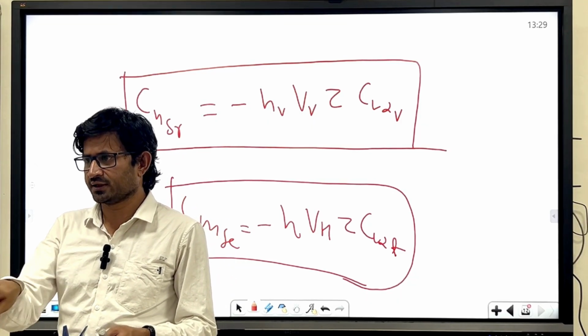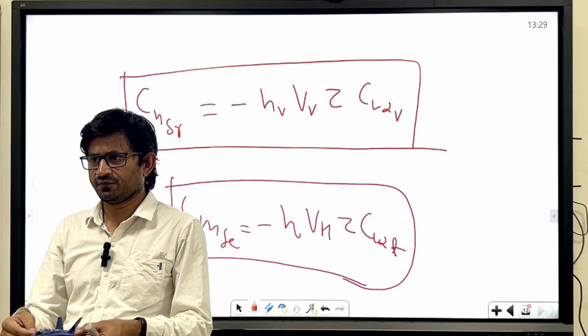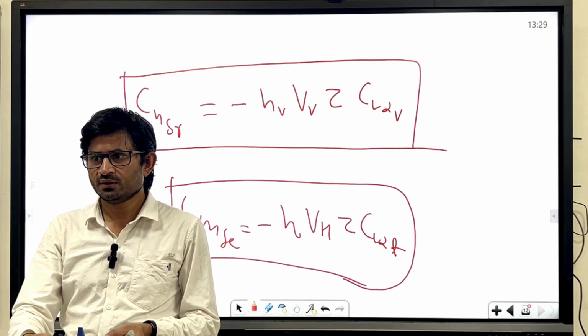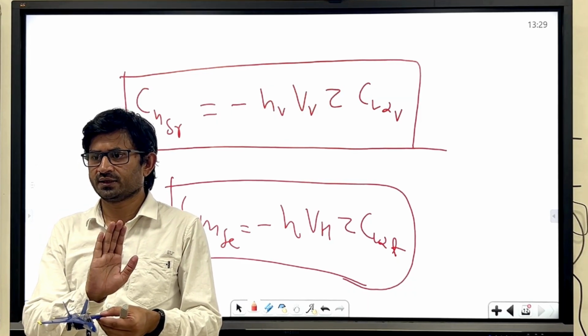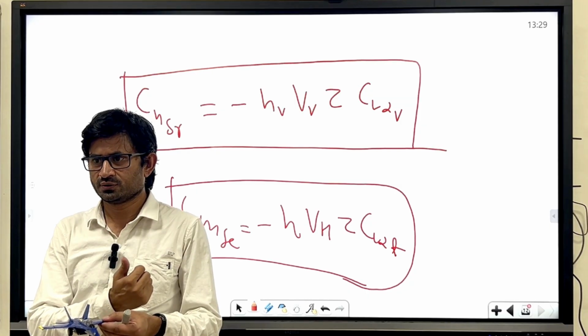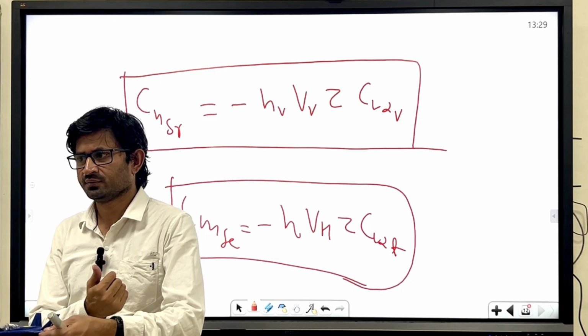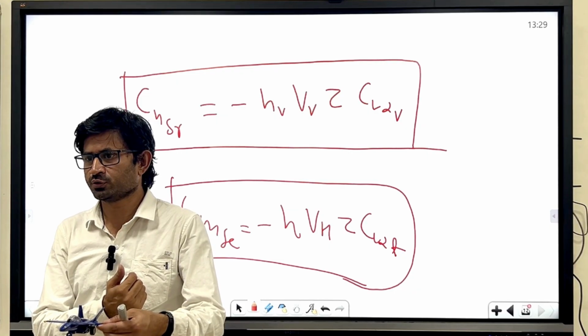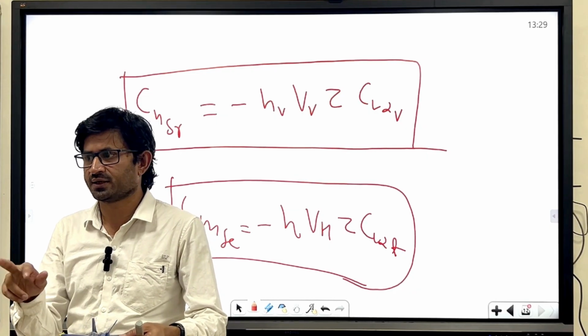Thrust is coming in this direction, right? So if this engine fails, the aircraft will try to take a yaw. So you have to counter that yaw. You have to deflect the rudder in this direction to generate the force and counter it, right? Okay.